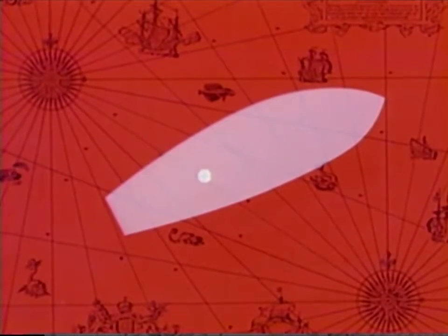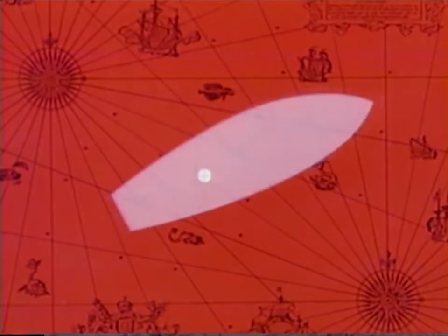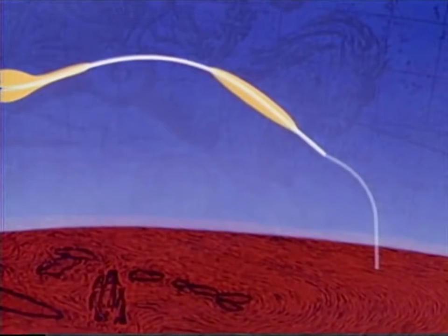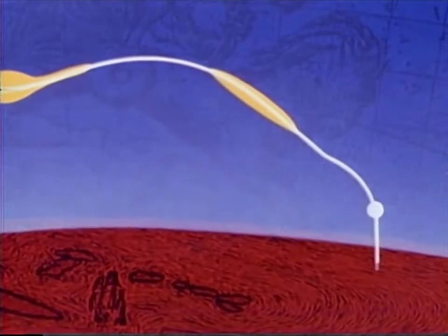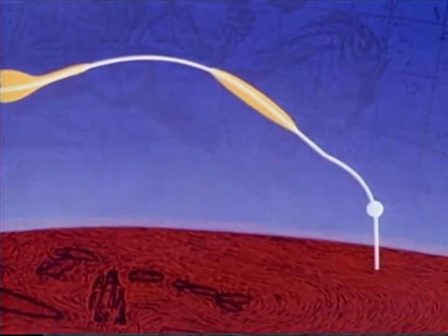That is, the spacecraft will be maneuvered to shrink the landing footprint, as determined during the first control period, so that the spacecraft will arrive at the target. The Apollo entry phase will terminate at about 23,500 feet altitude. At this altitude, the drogue chutes will come out, and the spacecraft will descend to splashdown by parachute.